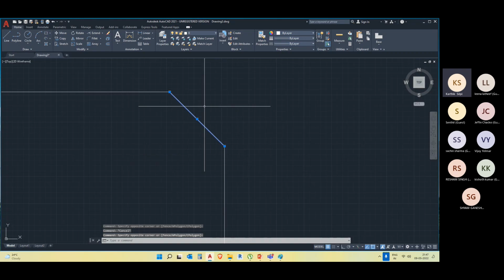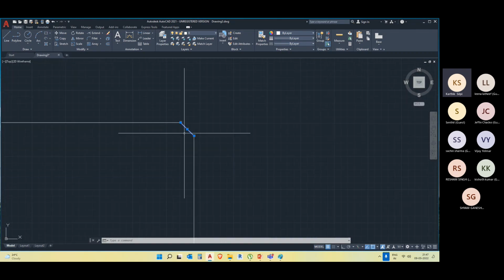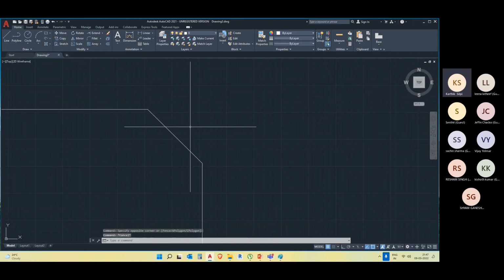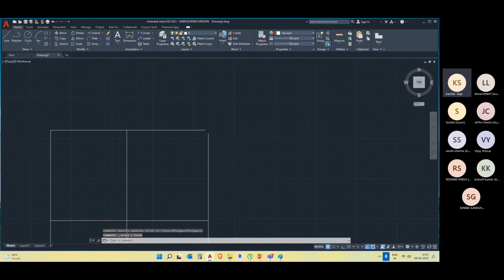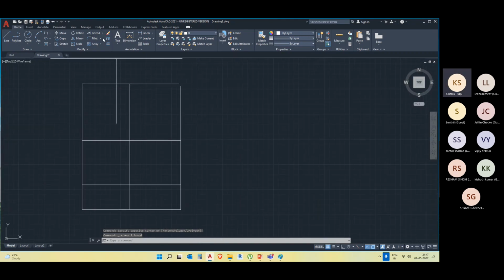This is especially seen in machining parts. When you machine a part, mostly they'll provide a chamfer instead of a fillet. That saves a lot of their machining capacity. Okay, that's what a fillet is. We can draw a fillet with multiple options, or there are multiple ways to draw a fillet. You can just give polyline, and after polyline you have to give the radius. Here I'll give, let's say, 150 mm.